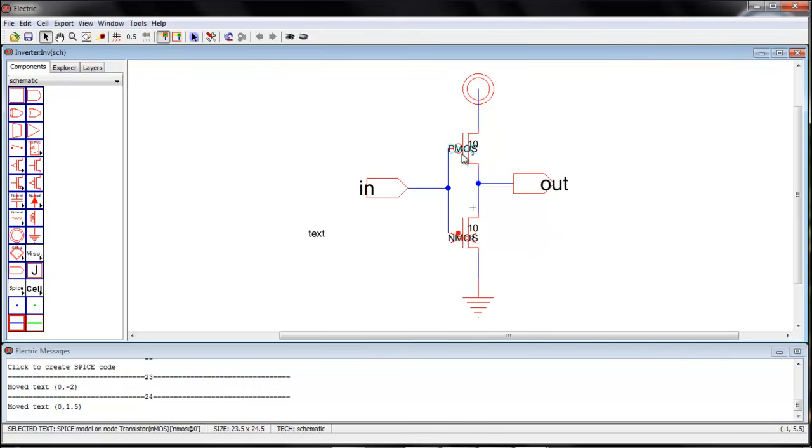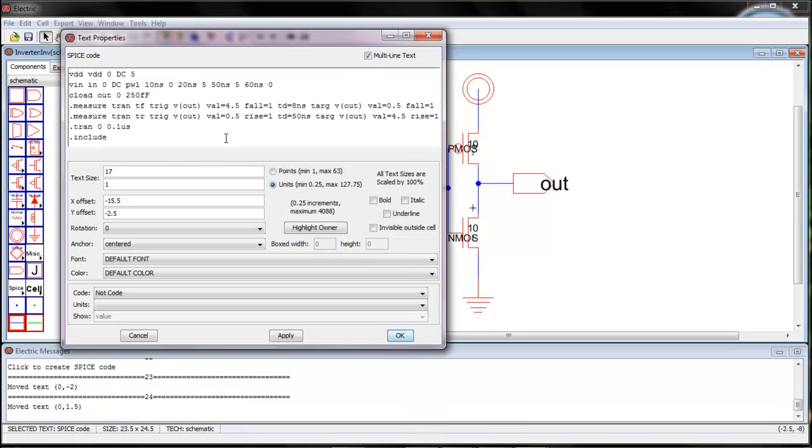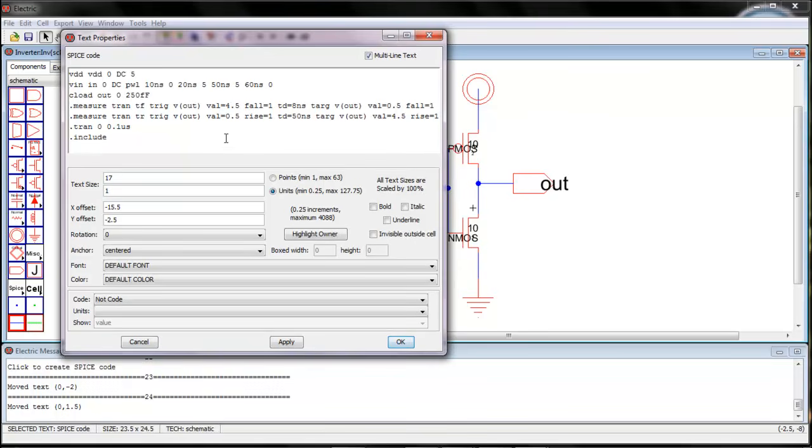This just means that we have specified that whatever is written for PMOS in the text files is applicable to this device here. Whatever is written for NMOS, like whatever the voltage thresholds, so we will say dot include the C5 models, and where is that C5 models text file stored? In the C drive, in the folder electric which we made.